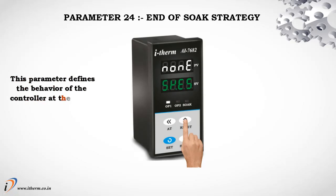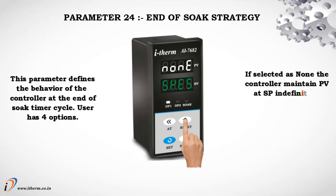This parameter defines the behavior of the controller at the end of soak timer cycle. User has 4 options. If selected as none, the controller maintains process value at set point indefinitely irrespective of start or at the end of a soak timer.